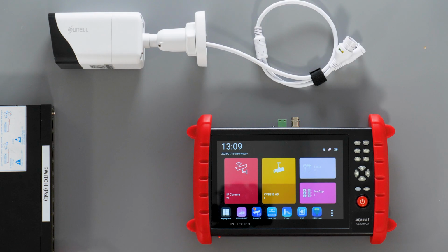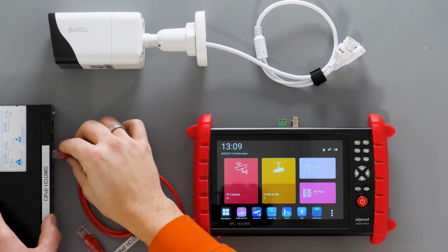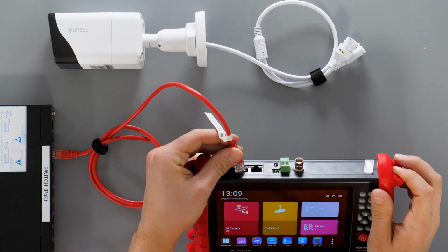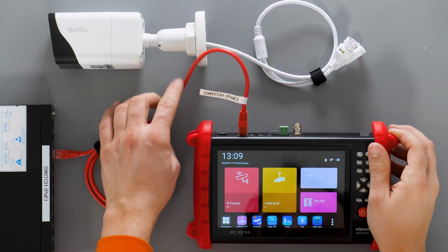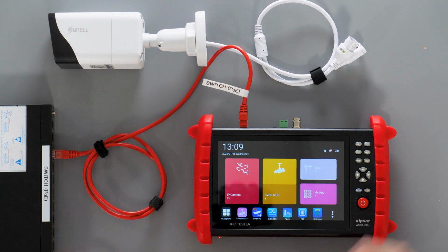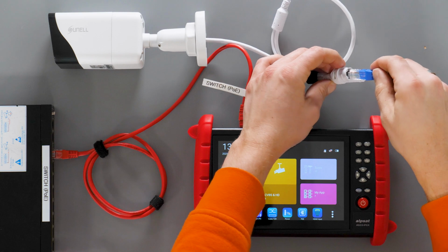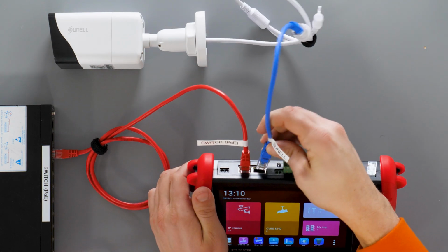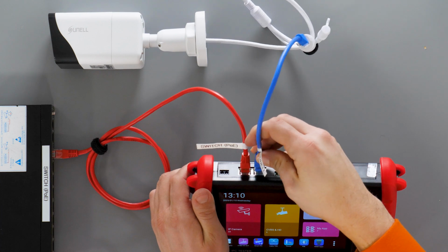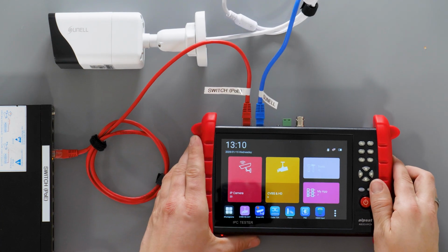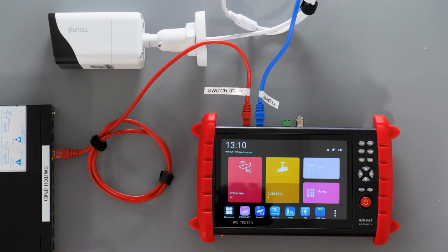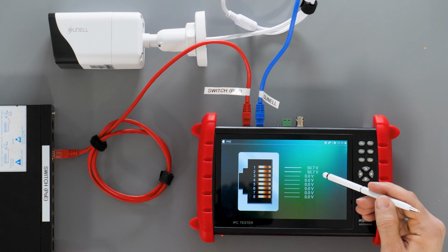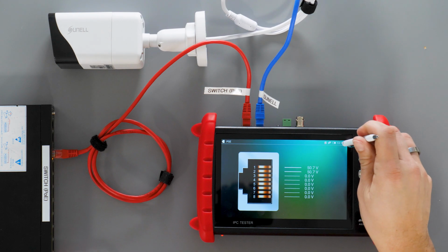The PSE application enables the identification of PoE wire pairs by measuring voltage. The PoE switch, which powers the camera, is connected to the PSE in port of the meter, and the camera is connected via the LAN port. In Power over Ethernet standard, power is transmitted using pairs 1 to 2 positive and 3 to 6 negative.